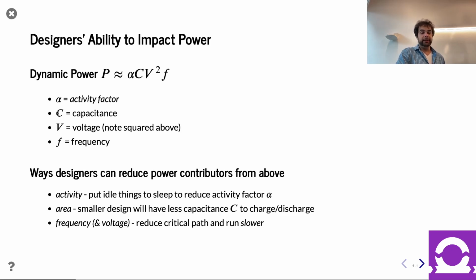The capacitance is a funny one, in that it's intrinsic to the circuit properties. There's an interesting trend. It's not foolproof, but it's a rough trend: for a given area across different process technologies, the capacitance is roughly the same. Not exactly, but roughly. The reason it's interesting is, wait a second, you tell me when I go smaller, I get more transistors.